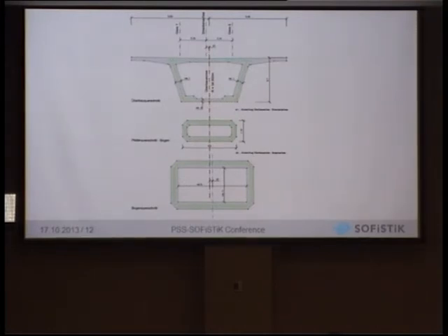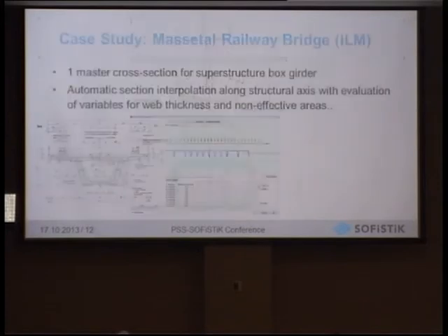You know, railway loads are quite high, so we want to check distortional effects and all this stuff. And furthermore, we have the eccentricity of these arch elements, so two sections here of the arch, which has another eccentricity, you see it here, towards the cross section of the superstructure. So we have quite an eccentricity of the train to the superstructure and furthermore to the arch.